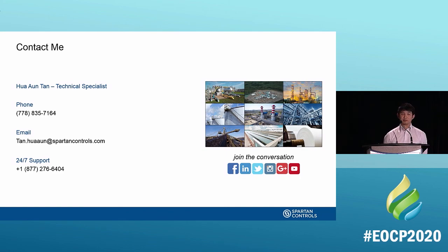Thank you. We have one question come in here. It says, what types of speed would those valves close at? Sky's the limit. It really depends on your application, right? So let's say an intake type butterfly valve that was, I'm going to throw out a number, 48 inches. Generally you want that actuator to close quite slowly because you don't want to shock the system. You don't want water hammer.